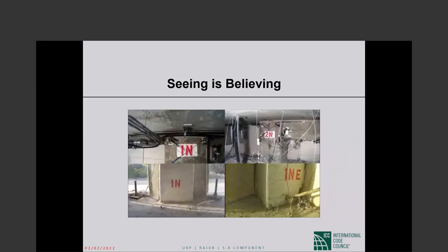In the counteractive load combination, 0.9 dead plus 1.0 E, we will have made the load factor 0.9 minus 0.2 S sub ds, which will come to 0.7 when S sub ds is equal to 1. So we will be decreasing the dead load factor in the counteractive load combination in consideration of vertically upward earthquake effect. So this we do for all structural members in seismic design, okay?